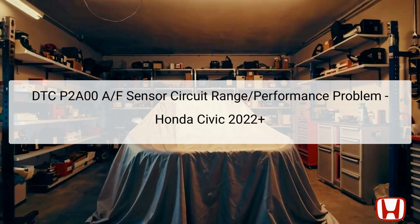This presentation addresses DTC P2A00, which is associated with an issue in the air-fuel AF sensor, specifically Sensor 1, in the Honda Civic models from 2022 onwards. When the output voltage of the AF sensor deviates significantly from expected oxygen concentration levels during periods of deceleration, the Powertrain Control Module, PCM, recognizes this abnormal behavior and triggers the code P2A00.